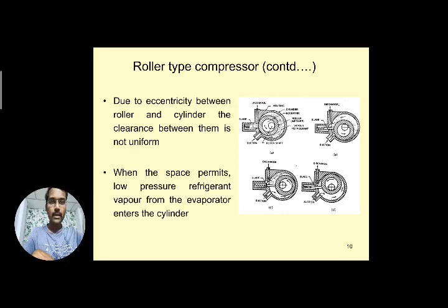So when the space permits, the low pressure refrigerant vapor from the evaporator enters the cylinder. It means when the space is opened, when some gap is provided at the suction port, the low pressure refrigerant vapor enters into the cylinder here.